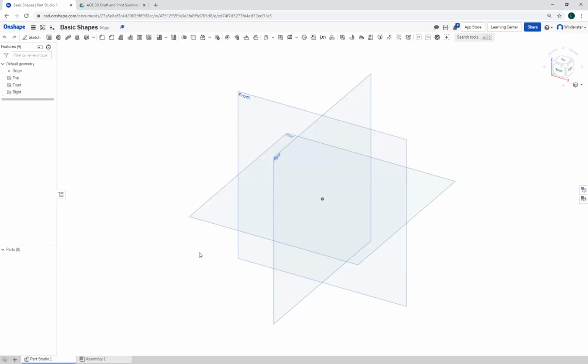On the left here, there are a couple of options you can do. Every single part, every single operation you do will be listed on the left panel. Right now you have the 3 planes and the origin. You can choose to turn them on and off. See the little eye? If you click on it, a crossbar goes through the eye, and you no longer see the plane.